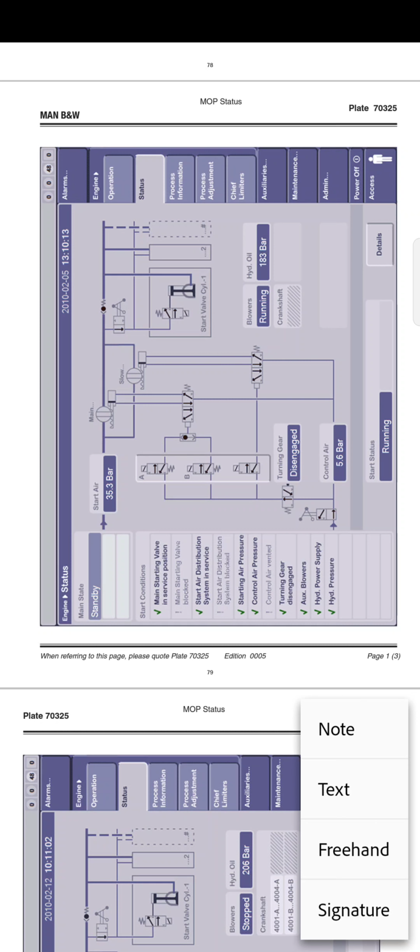And crankshaft position shows the current position of the crankshaft when turning the engine for maintenance purposes with the turning gear, and allows checking of the position in case of malfunction of the starting air valves. When the engine is running, the field displays the actual RPM. So here we can see all these things.